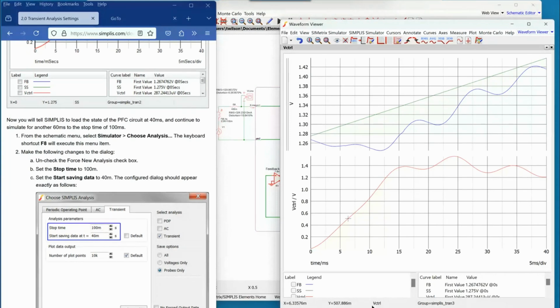So here I want to look at my PFC while it's starting up, look at a few critical signals and make sure, does this make sense? Does this make sense? All right. So we just did 40 milliseconds, and notice we're going in multiples of 20 milliseconds, which is the period of our 50 hertz line voltage. Okay. So now I want to keep going, and maybe go up to 100 milliseconds now.